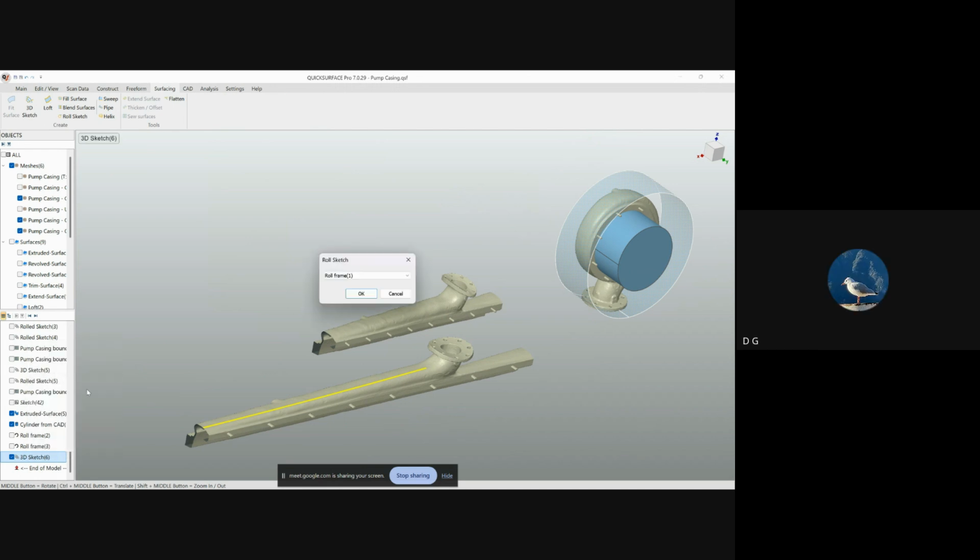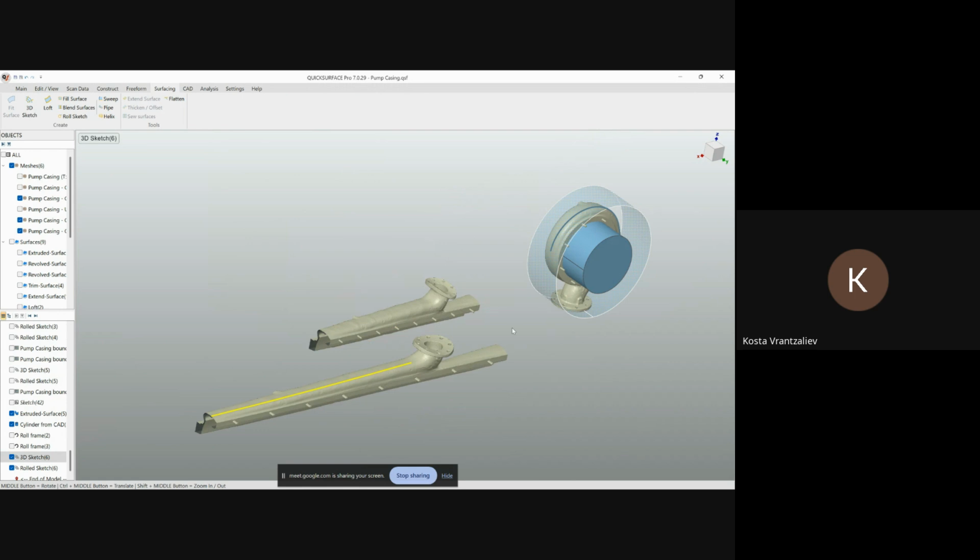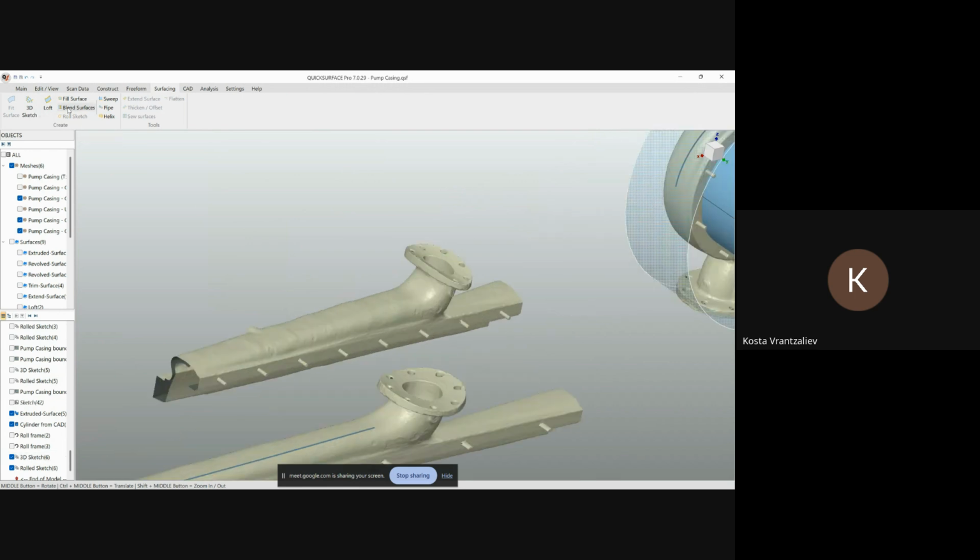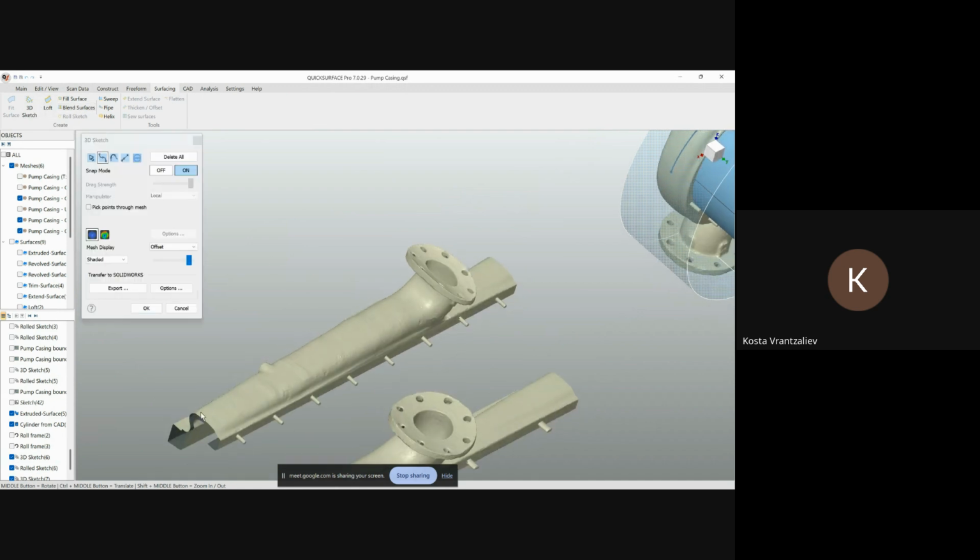But why do you need two different sizes of cylinders? I think one dimension is good enough. Yes, but sometimes you always try to fit the cylinder to where the features are, where you want to work after that. It will still bring it back, but maybe you lose accuracy, or you see that some of the holes are not exactly round, the other ones are smashed a little bit.